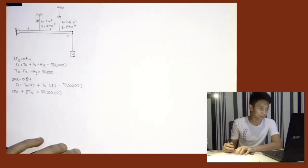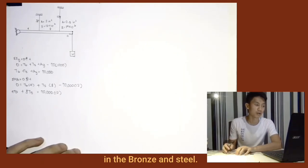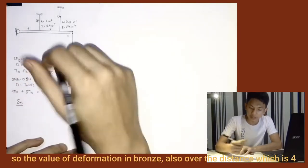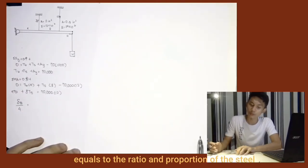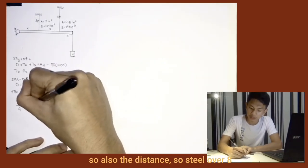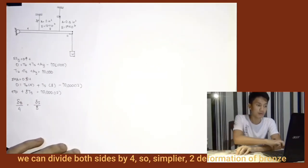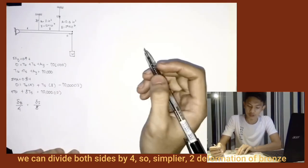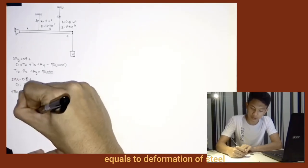So that's it. Next is by ratio and proportion, so we can get the value of tension in the bronze and steel. So the deformation in bronze over the distance, which is 4, equals the ratio and proportion of the steel, so the deformation of steel over 8. We can divide both sides by 4, so simpler, 2 deformation of bronze equals deformation of steel.